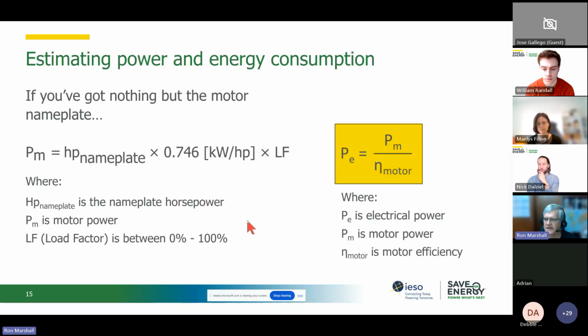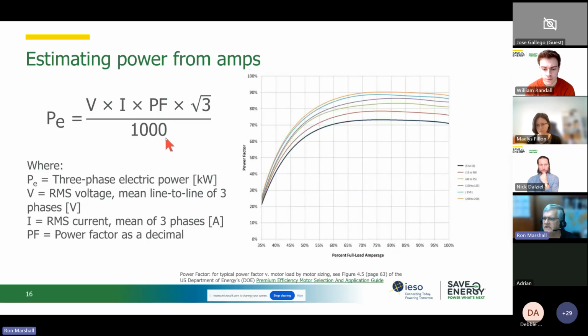And then if you know the operating time for the compressor during the year, you can project that forward, assuming that the compressor's in the same condition throughout the year, and multiply by 8760 or something and calculate kilowatt hours. And then you could take the kilowatt hours, multiply it by your electricity rate, and come out with the operating cost of one or more compressors using that simplistic method.